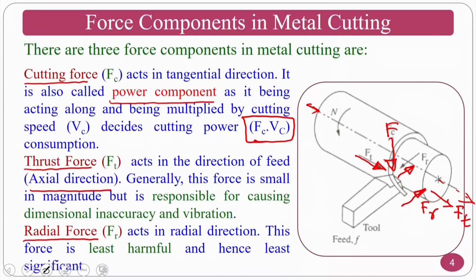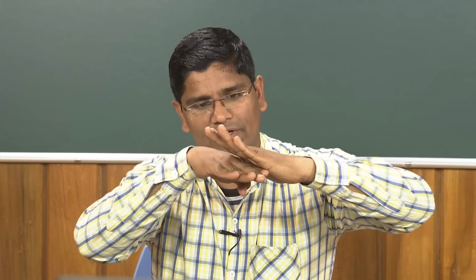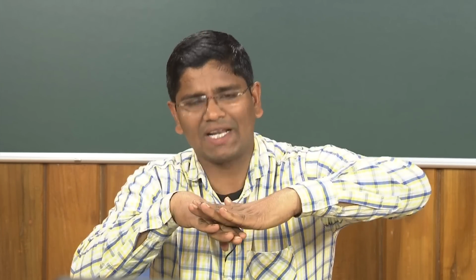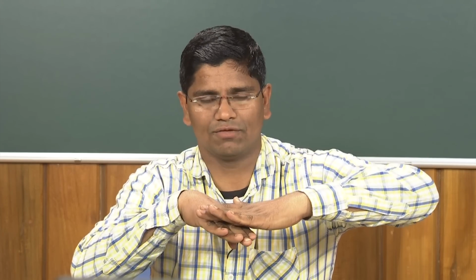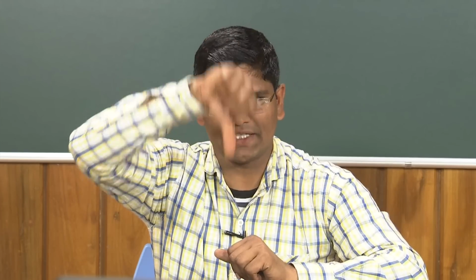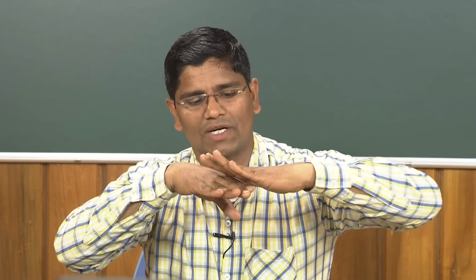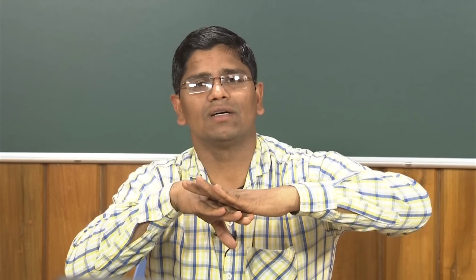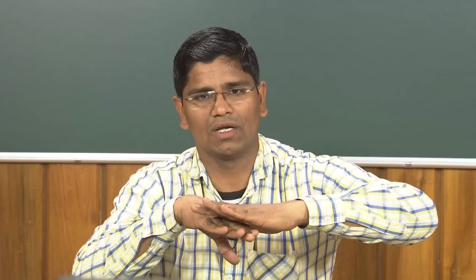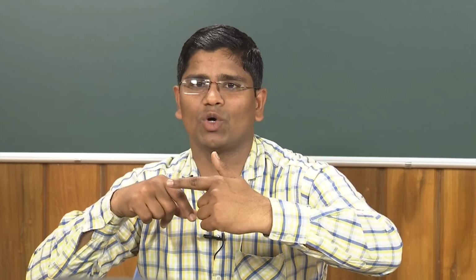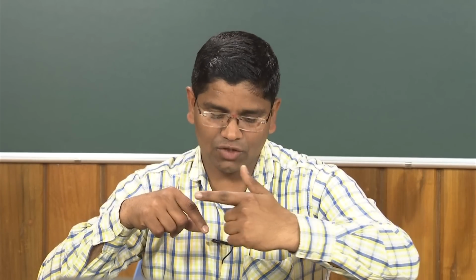Whenever I am cutting with the cutting tool, my chip is moving on top of it. In that case, my chip will kick down the tool. That is the cutting force, in this direction. The chip coming out kicks the tool downward, that is the cutting force. Along the axial direction of the workpiece is the thrust force, which some people also call the feed force, and the radial force acts radially inward into the workpiece, as per the depth of cut.